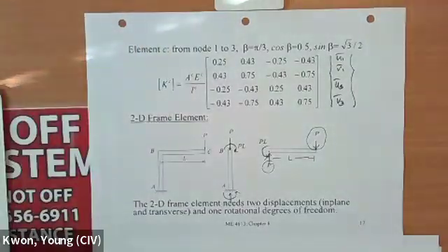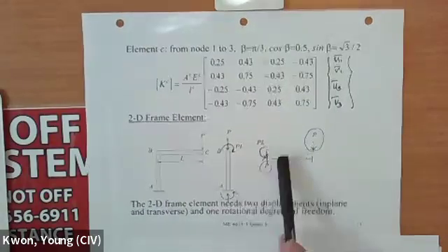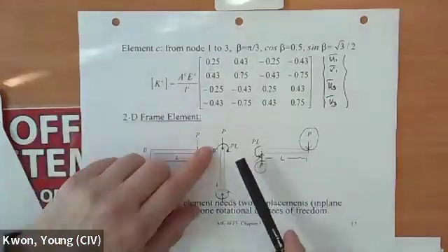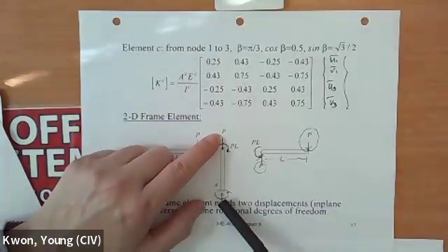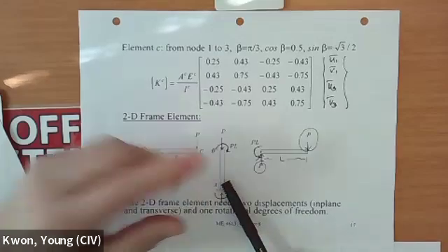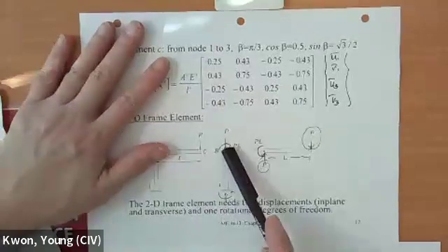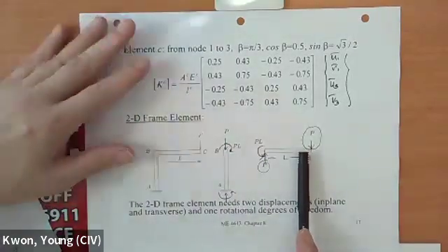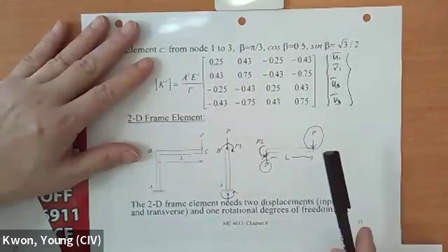All right, then how do you construct the element matrix for this kind of frame element? If you look at the frame element, what do you see? This force P in the vertical member, we call this the column. Somehow we differentiate that this is a column and this is a beam, but it doesn't matter. Both of them are basically the same type of structural element.